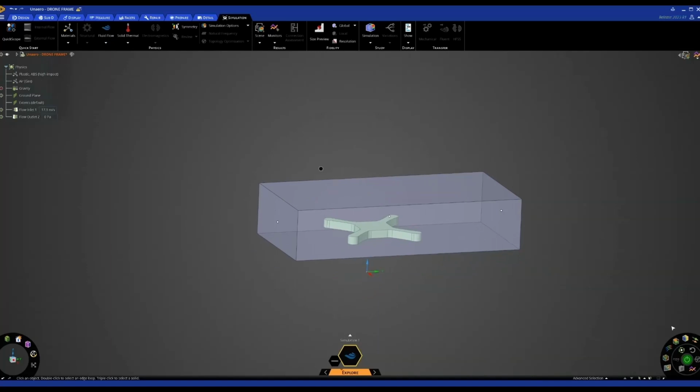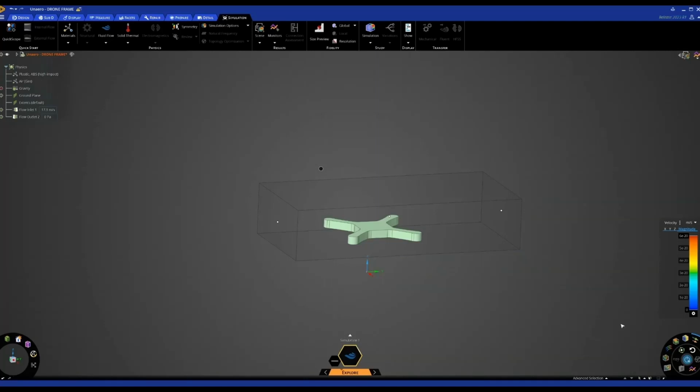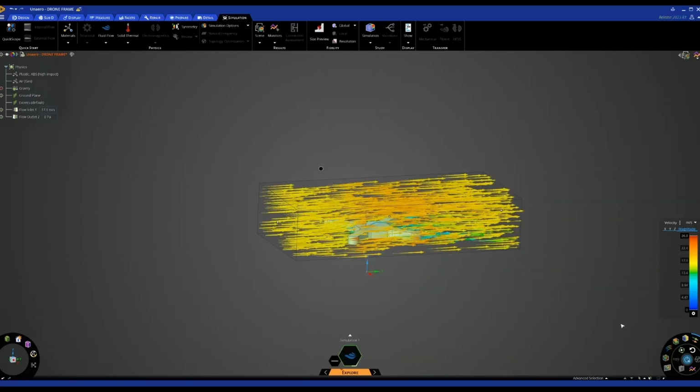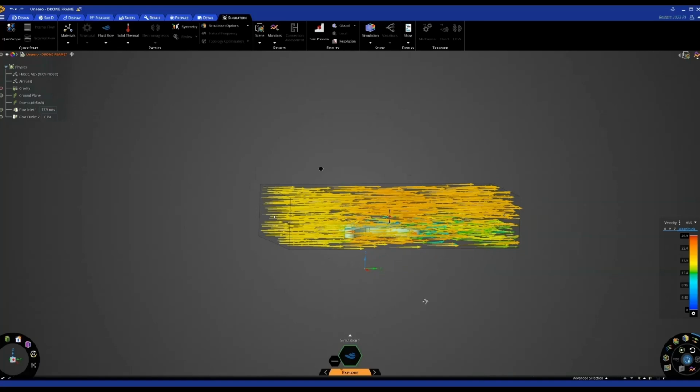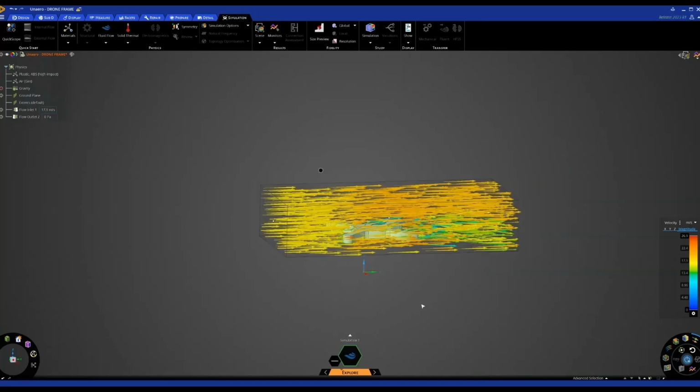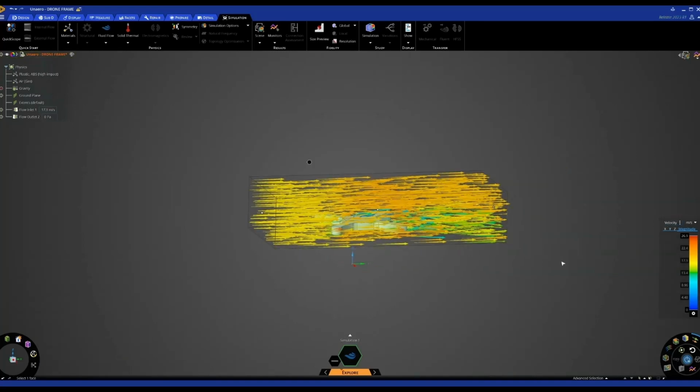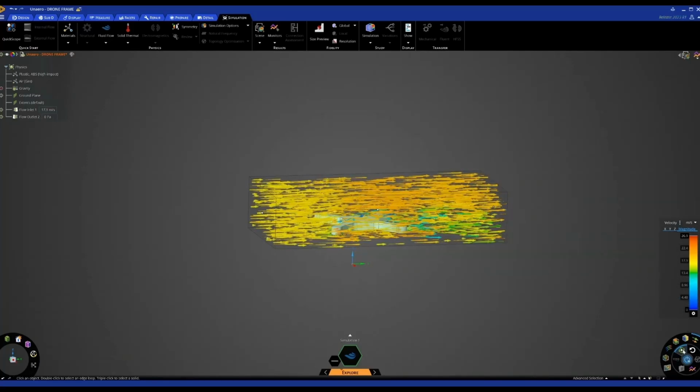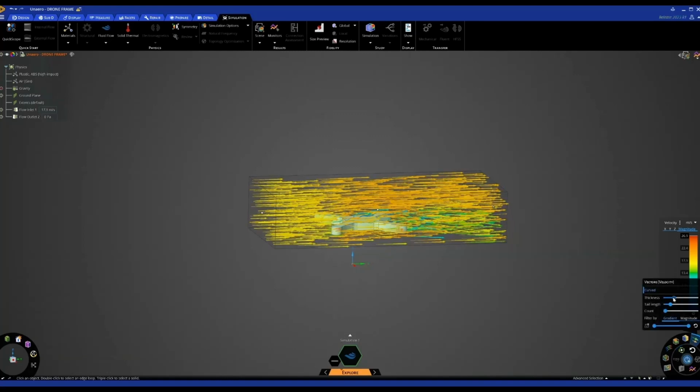We can now click our solve tool. Within a few seconds, we're going to start to see some results appear. Once this is complete, which it is now, we'll see our results. So at the moment, we're just looking at velocity, and we are looking at vector velocities. We can show an animation of these, and we can change all our simulation settings like thickness, tail length, count, and search, just looking for certain magnitudes. We can search for different areas. So that can all be customized to suit.